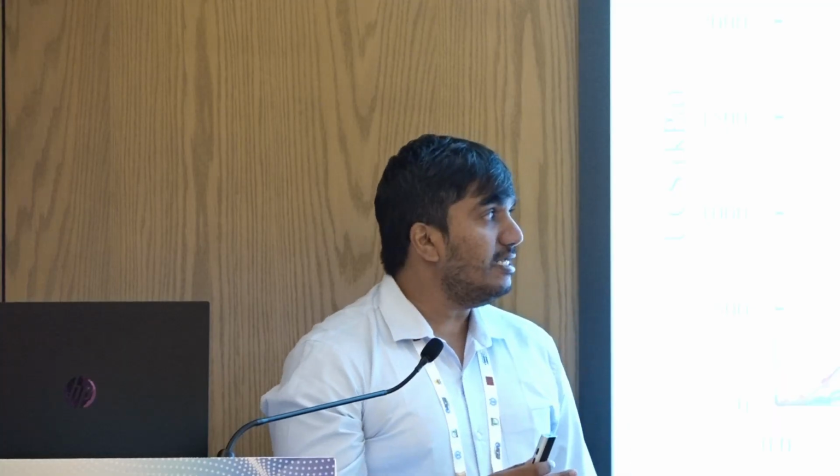In the active zone, however, the behavior is a little bit different. When you increase the curing stress to just 50 kPa, there's a marginal increase in UCS, but afterwards it shoots up once we increase to 400 kPa. There is an increase in stiffness as well. Although error bars are not shown here, we have done 3 trials for each test.